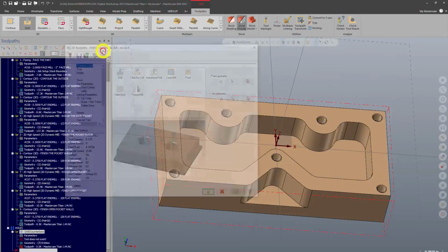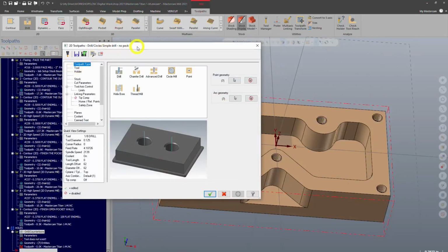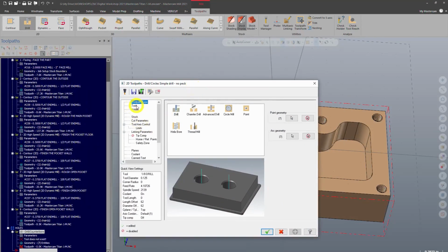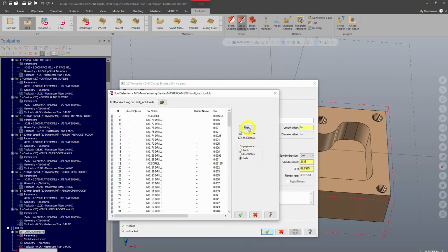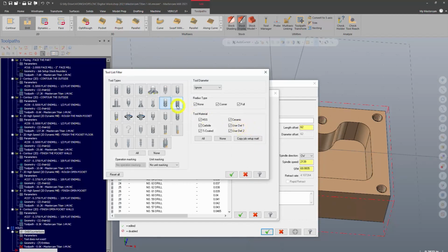We'll click OK. We're going into the cut parameters again. Tool, again, we're not going to be using an end mill, so we're going to be using a different type of tool. Let's filter, and we'll find what types we've got. So a chamfer mill, no. Taper mill, no. Spot drill, yes. You can either choose a center drill or a spot drill.